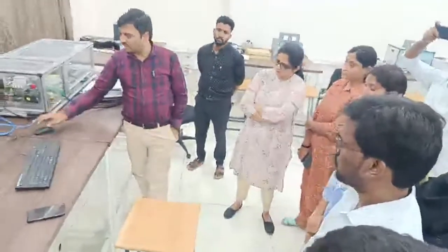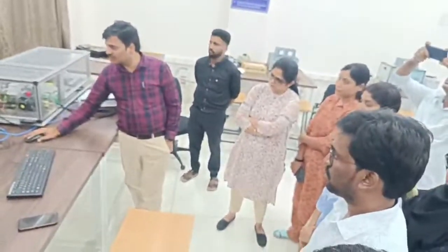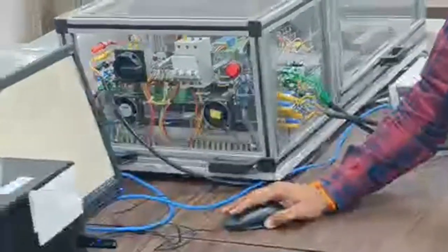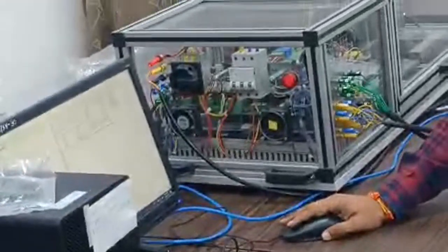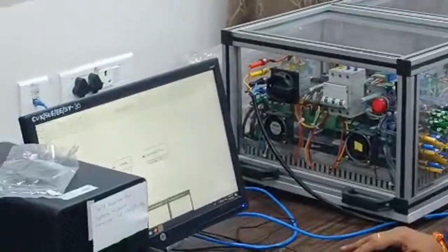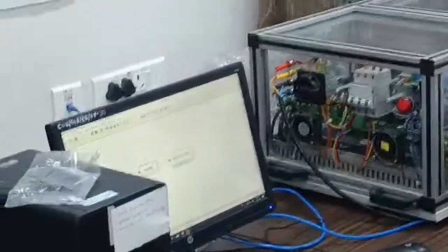DS1104. You have master, slave, express and this. I will take any one. You can use slave bit out, bit in. That means the pin acts as in or out. And you can see the PWM block, I told you PWM is readily available. I can use this PWM, we'll check that also. At present I have just given a simple bit out.